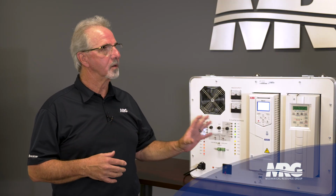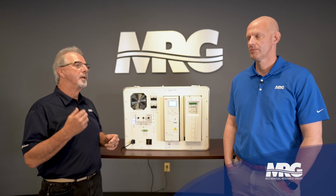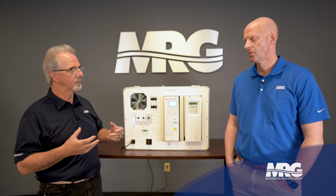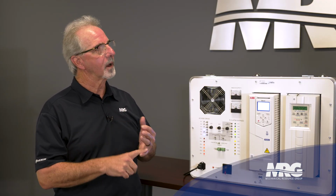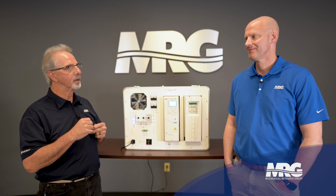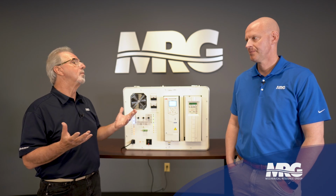The devices are not UL864, so it has to be controlled by a UL864 contractor, which is generally your fire alarm contractor. Now, AHUs and RTUs serve a dual purpose. They also supply cooling to a building and everything else. But in the event of an emergency, fire alarm comes in, air handler supply has to be shut down, and it's a hard shutdown. That means there's a wire that does not allow the connection to go to the motor. And then you have the return fan and the exhaust system that we'll talk about here in a minute. But the supply fan will get a hard shutdown because we don't want to feed a fire.